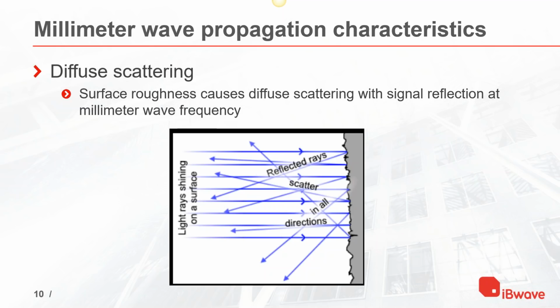On the other hand, if the wavelength is 30 centimeters, which is when your incoming wave is at 1 gigahertz, then a quarter of a centimeter doesn't seem like something that can concern that wave. It is very small compared to that wavelength. So that's why we consider that wall flat for those frequencies. So that is the difference between the wall at 1 gigahertz and the wall at 30 gigahertz. The 30 gigahertz wall may look like a rough surface, even though it is the same wall as if the incoming wave is at 1 gigahertz.